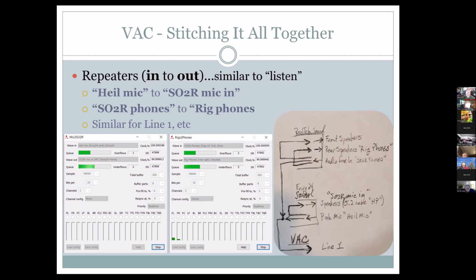You're throwing in delay, and each of these doubles the delay, because it has to transfer over going in, and then coming out when you listen to it. So it builds up quick. That's the reason you take the highest rate your computer is okay dealing with. And 48 kilohertz is not a problem for any of these things today. Unless you're running a Stone Age box, and then you're kind of hosed.